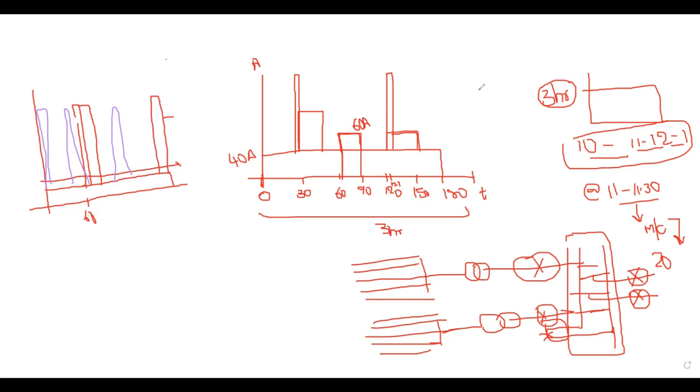But if you look into the sizing that we are doing as per IEEE 485, it says that the number of cells shall be selected depending upon the maximum voltage that the battery has to feed. Suppose a battery has to supply 220 volts plus 10%.